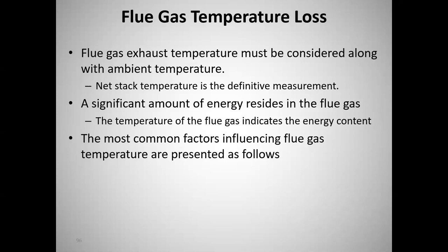to properly evaluate your boiler efficiency. Now, some people will have a temperature sensor way at the top of the stack, because the EPA wants to know the temperature of the gases that you're actually putting into the atmosphere. Well, that's good to know, but that's not the temperature we want to evaluate the stack loss, because that flue gas was probably 100 degrees hotter when it left the last heat exchanger, and it cooled down in the stack as it flowed through all the ductwork before being let loose to the atmosphere. That heat that's lost in between didn't do us any good. So when we evaluate the boiler efficiency, we want to know the temperature at which the boiler quits recovering heat from the flue gases.